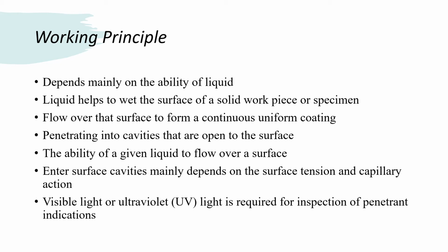Thus, the emitted light is in the visible spectrum, because the UV or ultraviolet light is not normally seen by the human eye. It is also called black light. The advantage of this in penetrant inspection is that regions holding a greater amount of the fluorescent penetrant appear very bright.